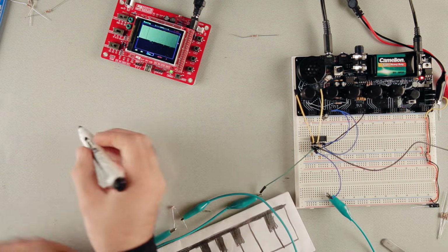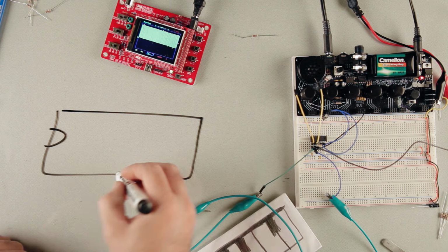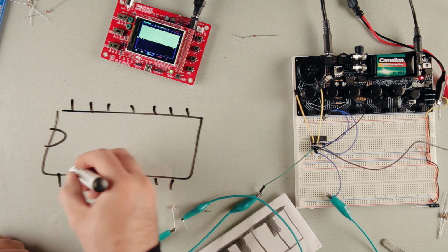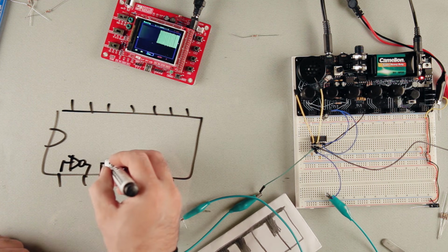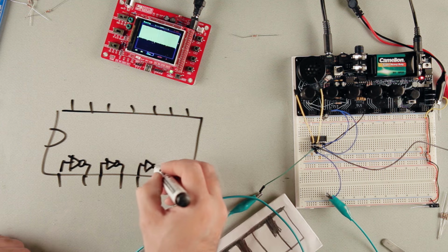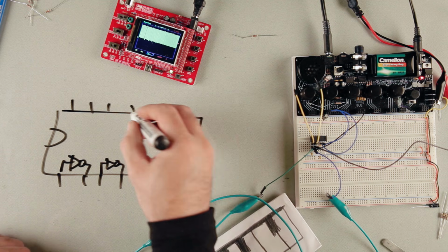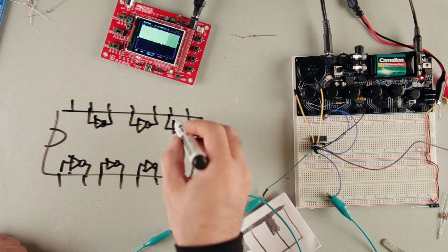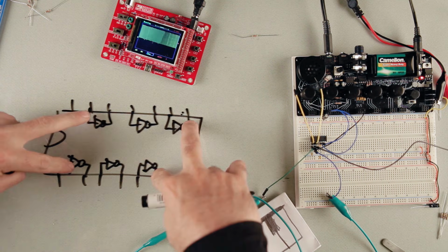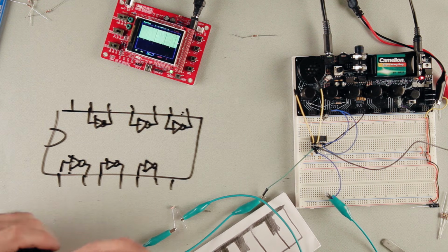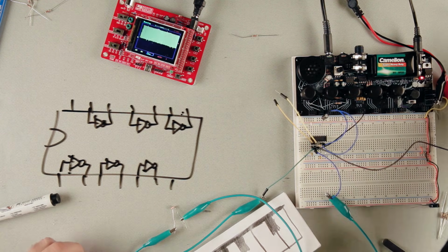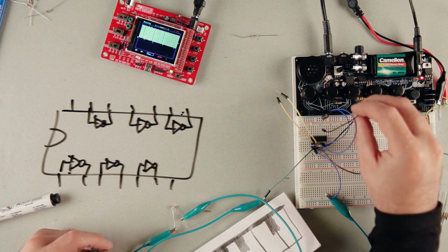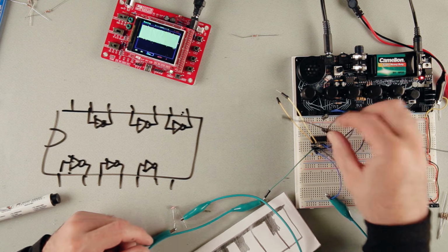So again, in our chip, we've got inverters all along the top and bottom. So I've used this one and this one, now I'm going to use this one here. I like to use the ones in the four corners because they're easier to get at. The ones in the middle are a bit trickier. So I'm going to take two more of my jumper wires, and I've put my capacitor in place. Now I'm going to put in a potentiometer so I can change the pitch of this.